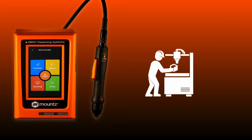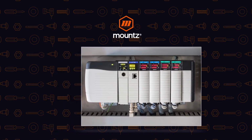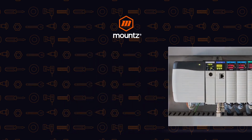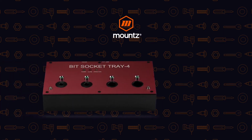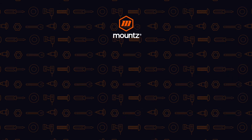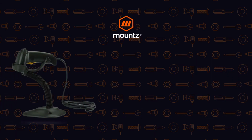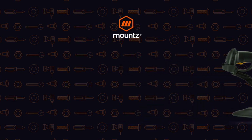So let's look at some of the different line control devices that we can incorporate into the assembly process. And PLC certainly can be done to be able to select programs, be able to communicate with the line. There also is the ability to use a bit socket tray, which as a bit is being used, it's automatically going to select a program. This same type of thing can also be done with a barcode scanner.